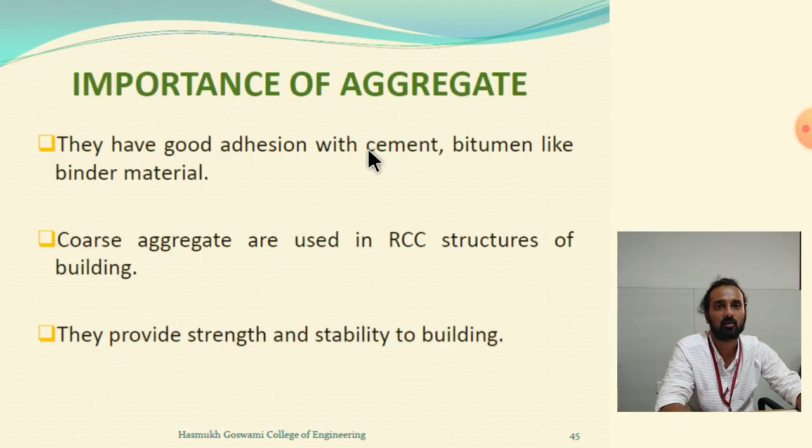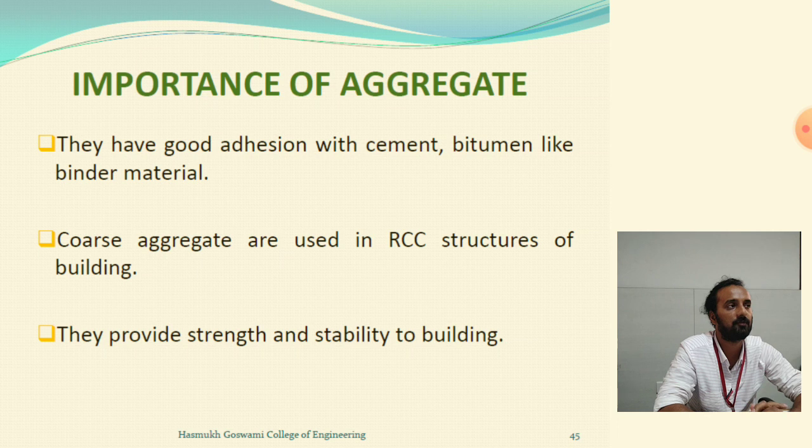Yes, importance, of course. What is the importance? Aggregate, as I said, 15,000 tons of aggregate is just used for a school building. So we can imagine how many buildings there are and how much aggregate we need, and it's in huge demand. So of course there is much more importance of aggregate, sand and all these particles. They have very good adhesion with cement and bitumen-like binder material. Coarse aggregates are used in RCC structures of buildings. They provide strength and stability to the building.